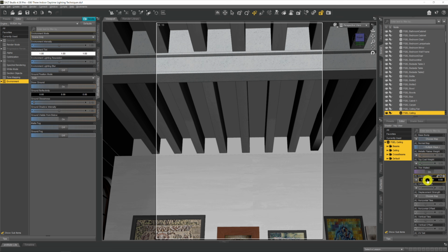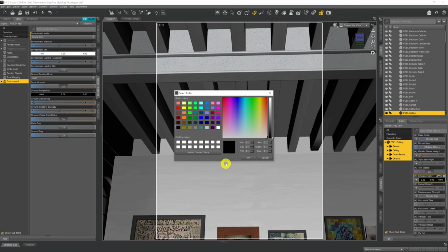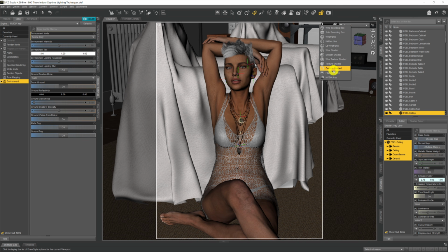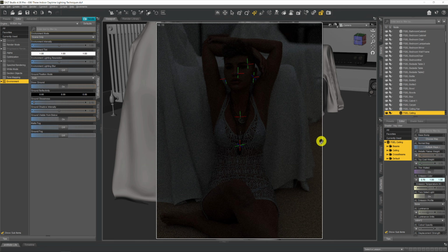And what that'll do is turn each of the surfaces here into an emissive. So if we come down to that color and say we'll turn it into white, no, I'll tell you what, we'll make it a slightly blue light, and we'll click OK once we've done that. If we now come back to our camera and come across to Environment again and give that a click, we can see that we get this fairly dull and dim lit scene, all being provided from the light that's coming from that ceiling.